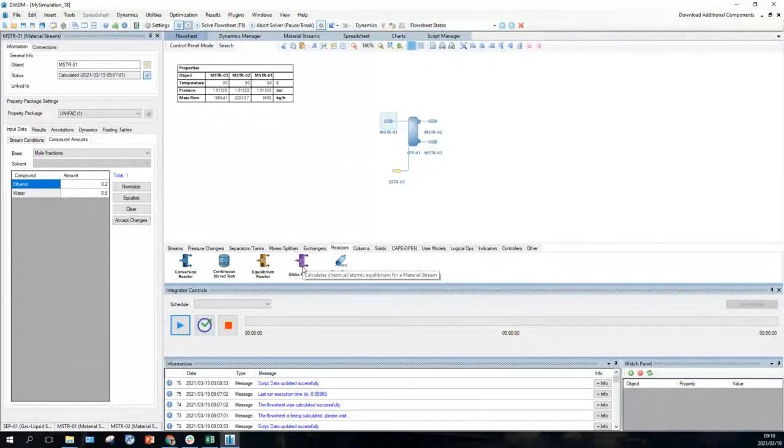It is a useful thing to see if it is thermodynamically possible to get a certain conversion. If it's not thermodynamically possible given a certain feed, that's what you'd learn from your Gibbs reactor. You also will see what temperatures are favorable. For instance, it may be that you need to operate at a temperature below a certain threshold to get a certain conversion. So a Gibbs reactor is useful to have.